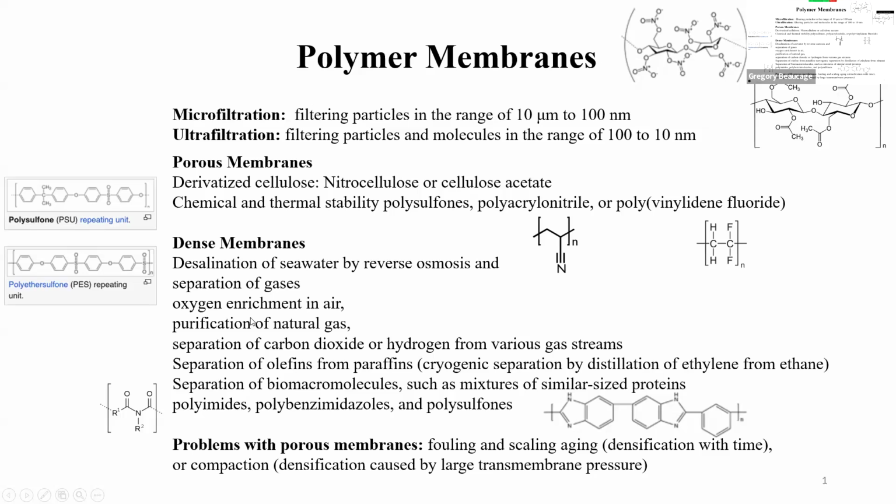So anyway, within the polymer area, you can look at porous membranes. If you're on the micron scale, human hair is 50 microns, so it's like human hair thickness pores in a material. You can do that in a variety of ways, and you can do it by phase separation. Typically polymer phase separation is going to be in the 50 micron range. And there are different kinds of phase separation. You can do it by thermal phase separation. So you have something that's miscible at a certain temperature, and then you drop the temperature and it phase separates. And then you can somehow wash out one of the phases and end up with a porous membrane.